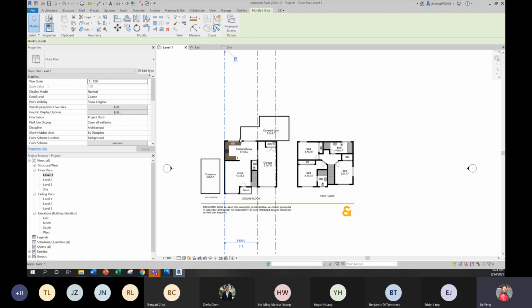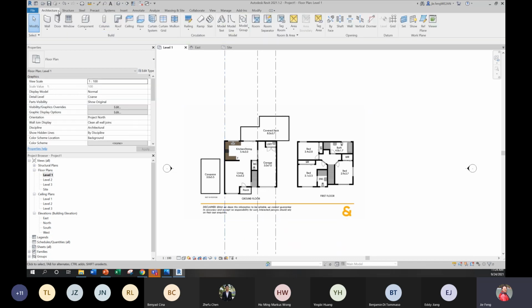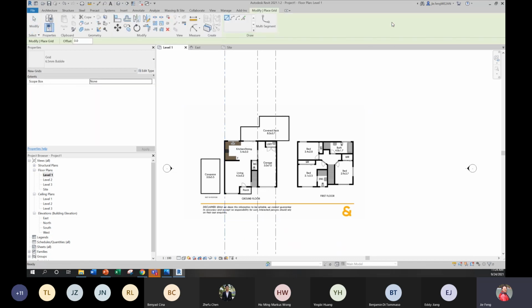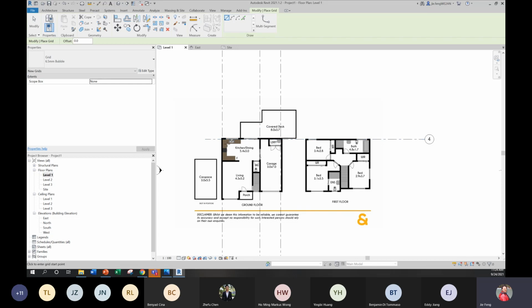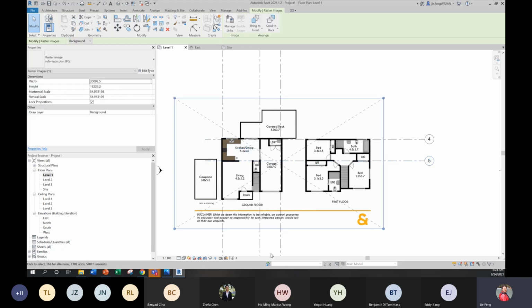And let's do the horizontal things. The same as the vertical grid, start with a horizontal grid. And this is 5.4 by 3, so the second grid should have the distance with the first one of 3. Let's right click, create similar, start from this side, and then change the dimension to be exactly 3 meters.